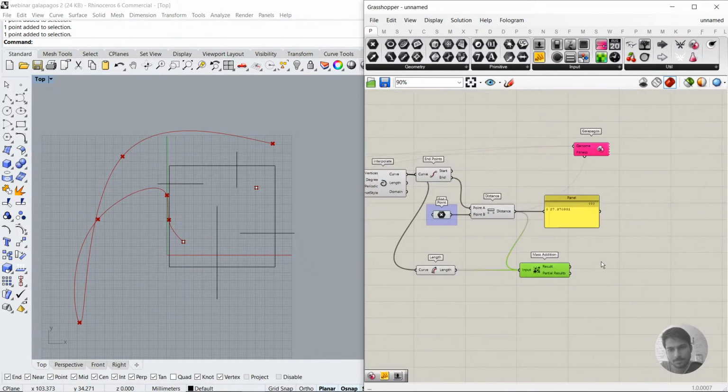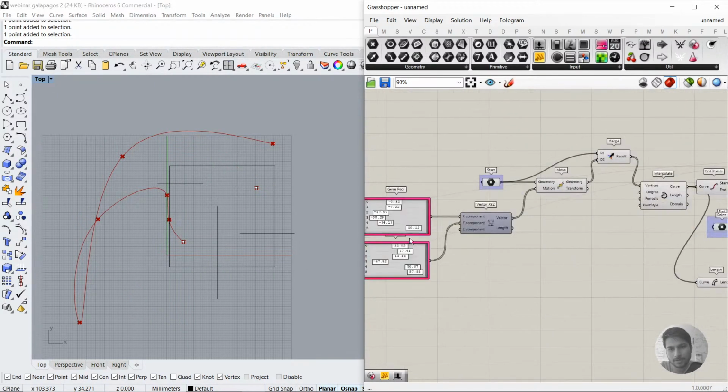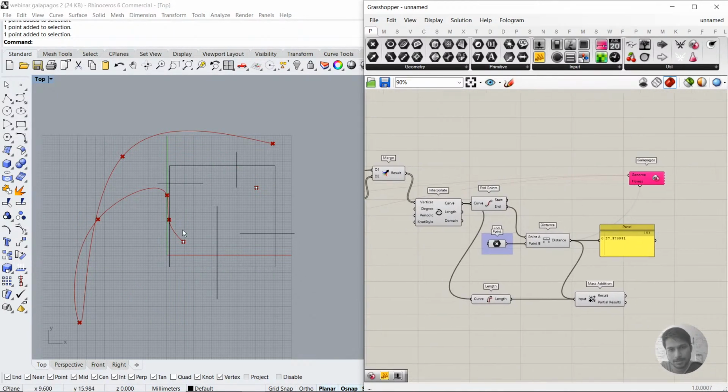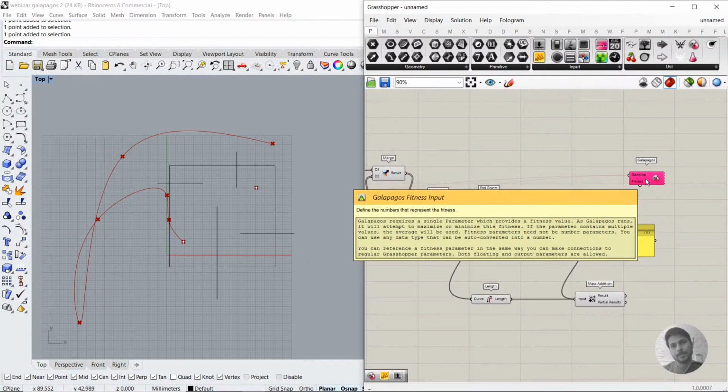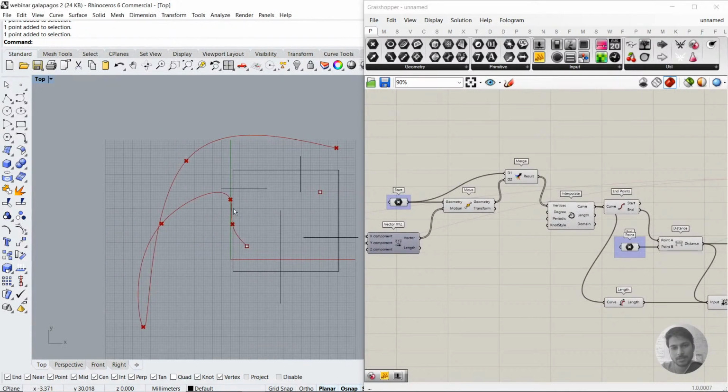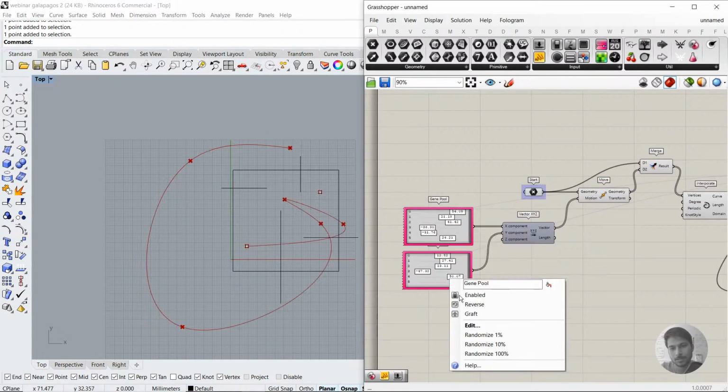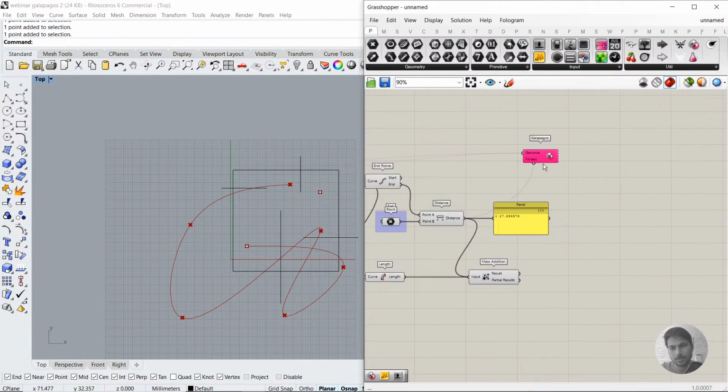Let's randomize, because if you don't randomize and if you start just with the past value, the solver is going to take that initial value in the first generation, and it might create dominance already in the first generation. So make sure to randomize every time before you start running the solver.